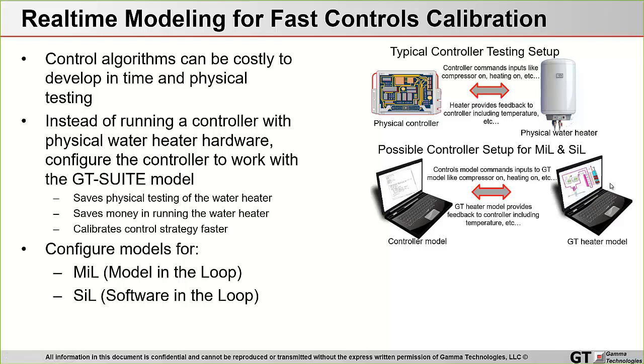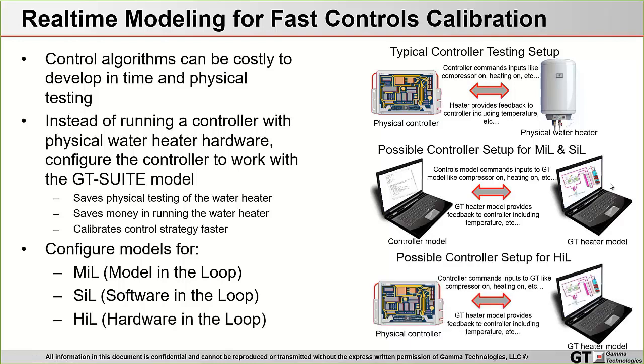And then for the ultimate step, there's the ability to do hardware in the loop simulation, where the physical controller, instead of talking to the physical water heater, is now talking to the virtual water heater model with GT. And that allows users to quickly analyze the controller performance and hone in on a proper design.